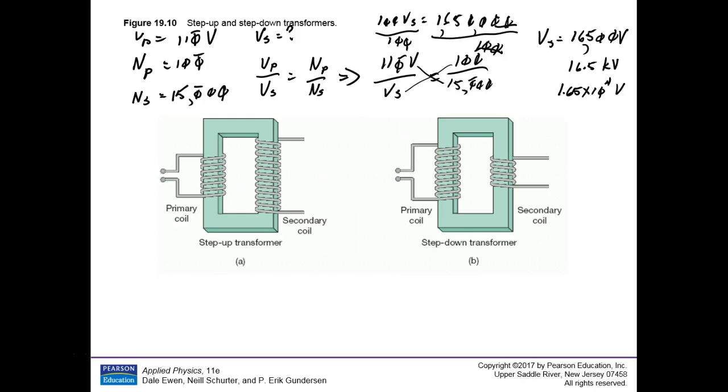Okay, and then there's another thing. When the mass of metal, the core, is subjected to a changing magnetic field, what they call eddy currents are set up in the metal that do no useful work, waste energy, and that kind of stuff. So they talk here about laminating the core to reduce the eddy currents. That's not really all that crucial.